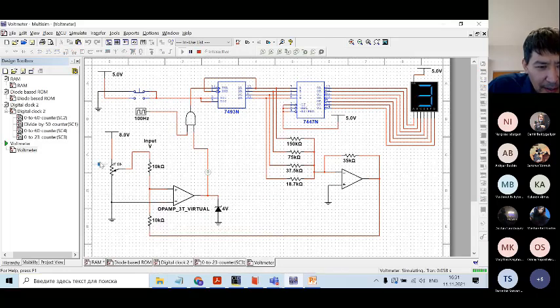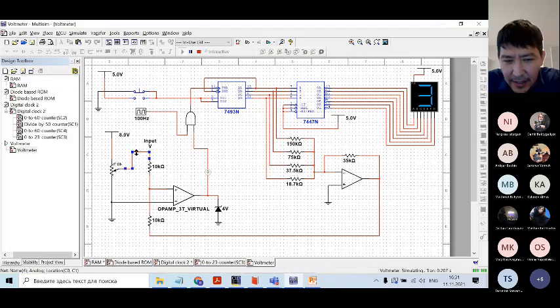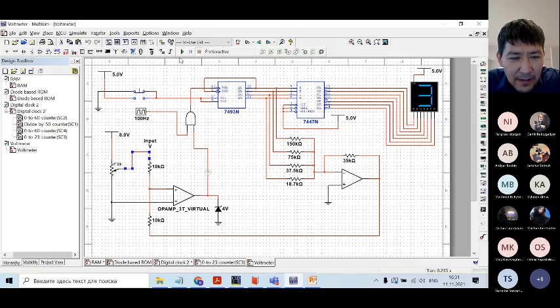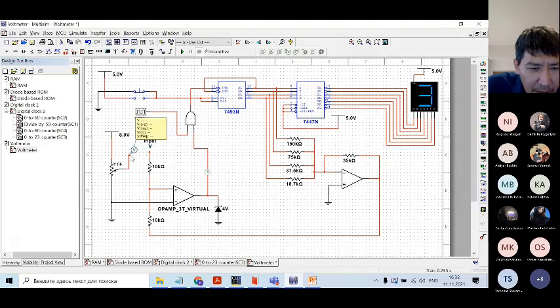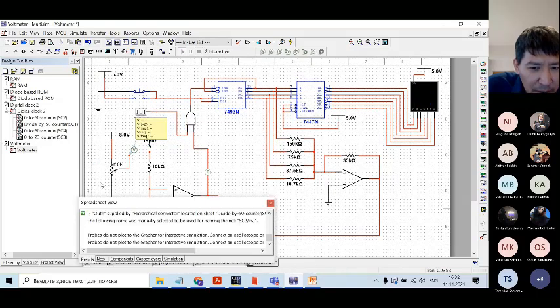So here is a potentiometer. I want to measure the voltage. So actually, let me just for a while remove this and explain to you. If I connect this to some wire when I want to measure voltage, it should show here on this display. Here we call this a potentiometer. It has a wiper. If I move the wiper, my voltage will change.